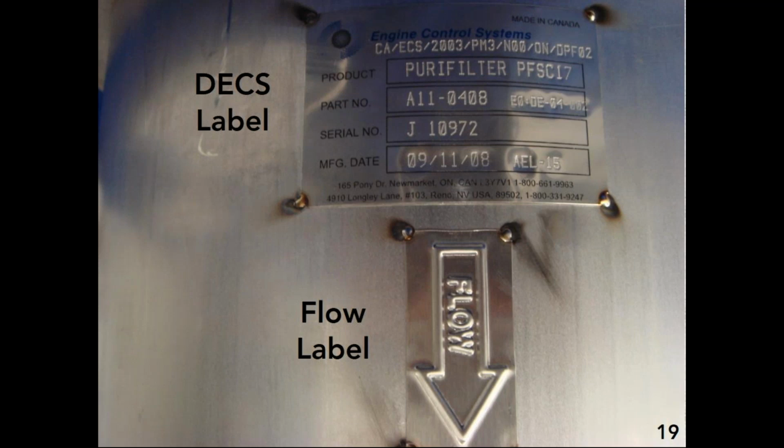Interestingly enough, you'll also see, this is for a retrofit on a filtration, that is a filtration system. You'll see that plate on there, but you'll also see a flow diagram. That's because we had people who were putting these things in backwards, sometimes purposely, and it was causing some problems with particulate emissions. So when our enforcement officers are out in the field and they see a retrofit, they will look to make sure that that arrow is pointed in the actual flow of the exhaust that the engine is producing.